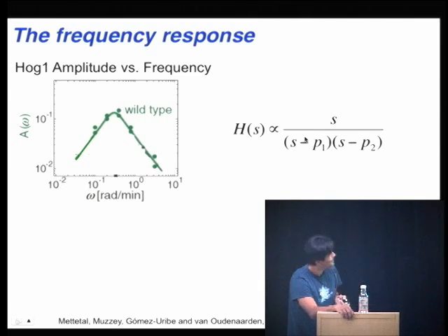Why is that interesting? It's interesting for various reasons, but I think the most interesting one is that you can then apply another very useful result, the final value theorem, which tells you what the steady state level will be for an input response of a given magnitude. And that's obtained by simply evaluating this function at s equals 0, at the frequency 0, to get the DC offset, multiplied by the gain of the input, by the magnitude of the input.